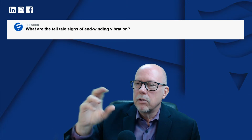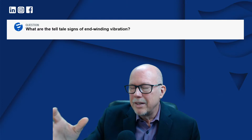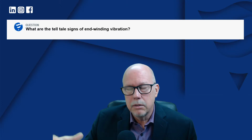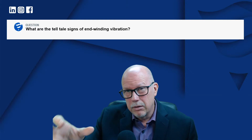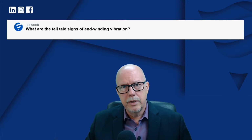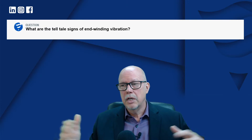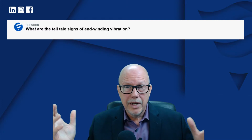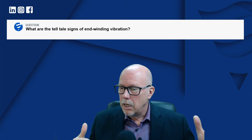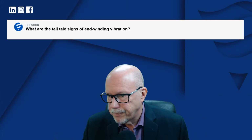So if you have localized dusting or greasing around the support system or next to the core, that usually is caused by fretting, and the fretting will create the dust. And again, if it's humid, it'll create this brown grease that you see leaking. Another telltale sign, which is a little more complex, is when you go in there and there's dusting everywhere, all over the place. So either you have vibration generalized everywhere, or you have some vibration in different locations, but the ventilation is just carrying the dust all over the place. Well, if that's the case, you evidently have a problem with vibration.